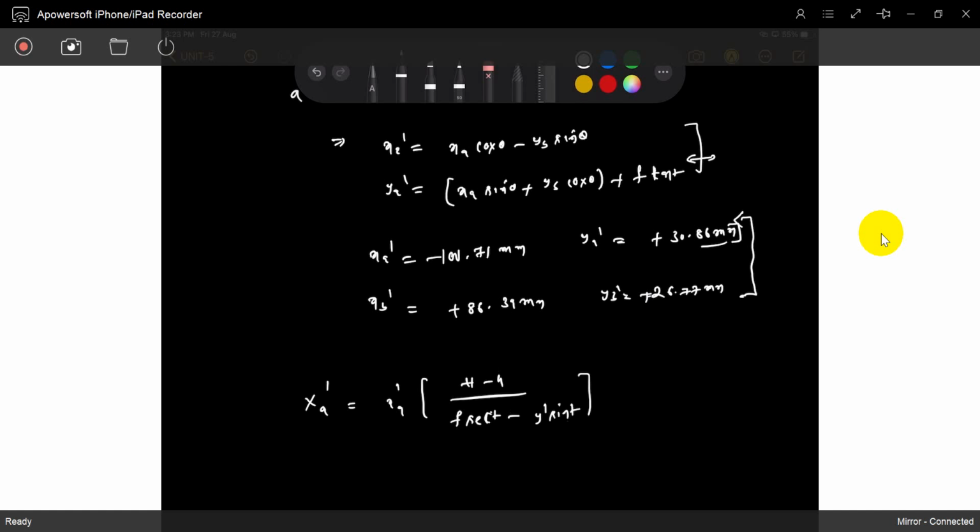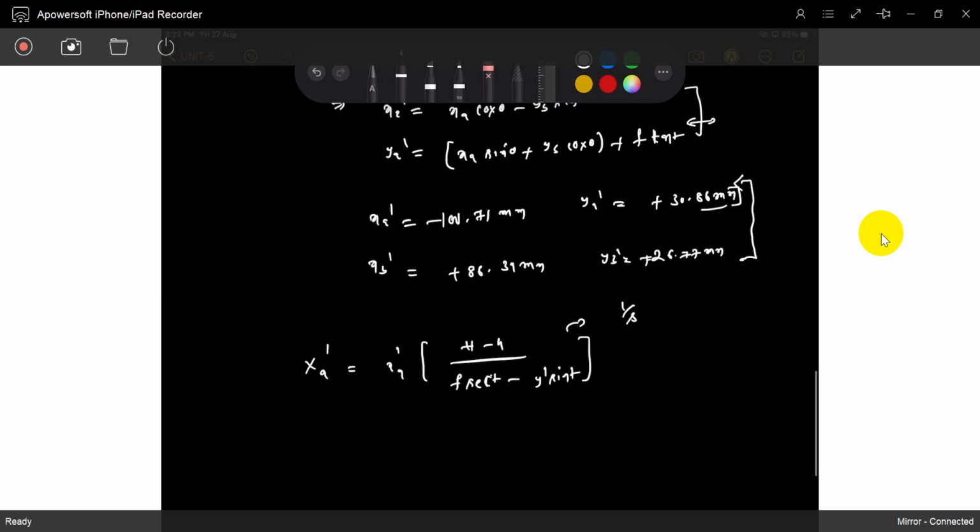That is the scale, so the opposite scale is 1 by S. You will get the coordinates on the ground. If you want the coordinates on the ground, you multiply with the opposite of the scale. Otherwise, if you know the ground coordinates and want the coordinates in the photograph, multiply with the scale. That is the meaning of the scale, increase or decrease.